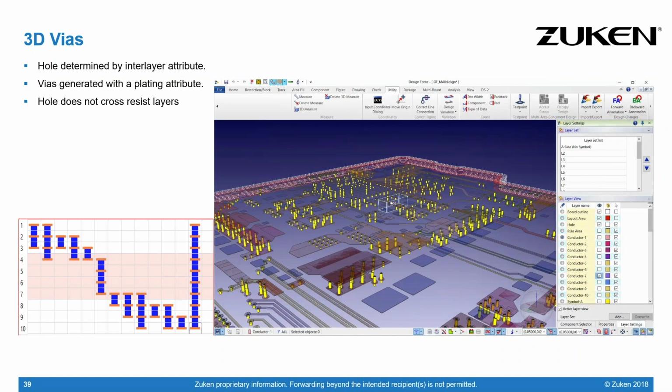Let me make it a simple thing. If you have a signal, it's not just electrons going along; it's actually an electromagnetic wave which has a signal and a reference. So we need to think about where the reference is. If you have an ideal ground plane and a signal traveling over it, you're good to go. But how about a multi-layer PCB, maybe 8 layer, 10 layer, 14 layer, where a signal via goes from the top layer to the bottom layer? Where is the return path for the signal via? If you do not have a close-by stitching via that offers a return path for the signal via, you are going to get all those kinds of signal noises. So vias become more critical in DDR5 high-speed data transfer. This is one of the key parts when we design this DDR5 layout.